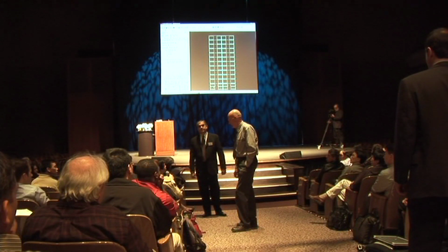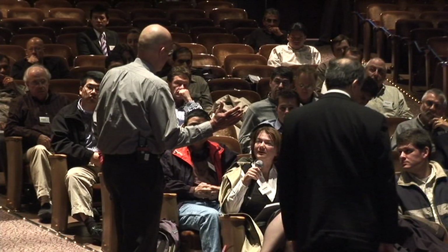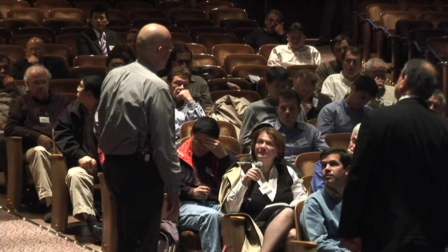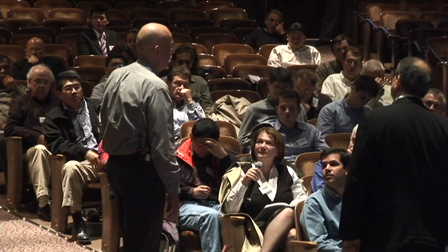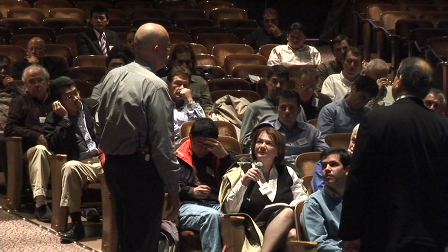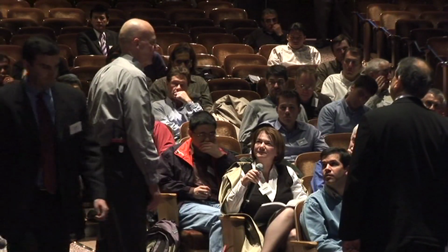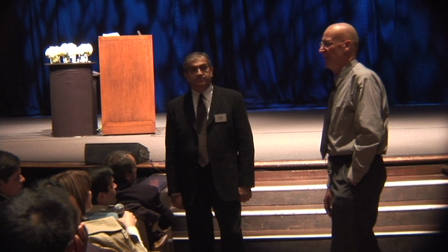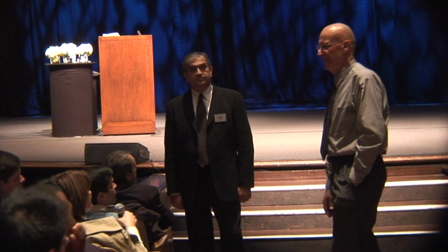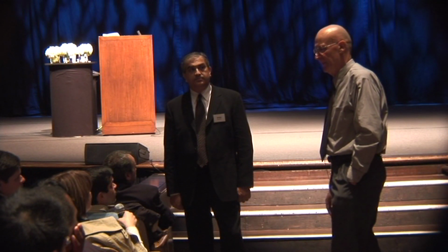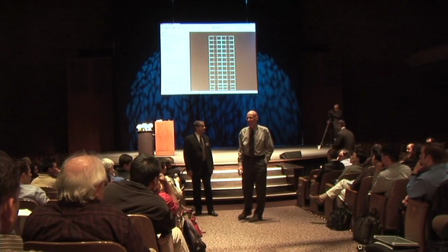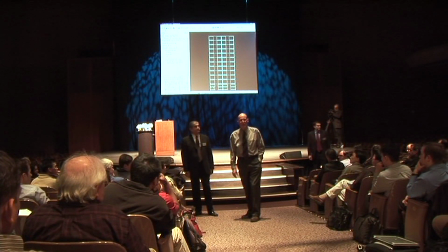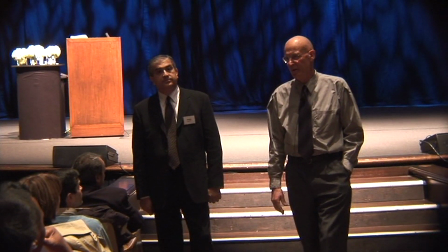The ATC-63 project ran a whole slew of different records, and on their model they didn't use Perform. They used OpenSees, but they observed the same thing. They did statistics, and very few failed by hinging at the base. I think it was roughly 50-50 shear at the base or hinging higher up. And say Professor Krawinkler pointed this out quite some time back, that you do get this effect. And it's one of the things that sometimes linear analysis can give you a wrong result.